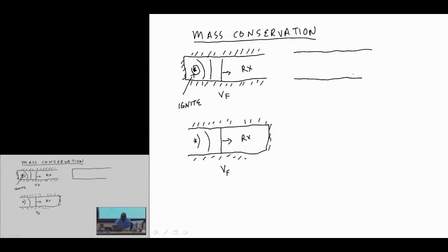So, we have this observed flame velocity. The assumption is that we have, in this case, again, just like in the bottom case, a burnt gas over here. We have an unburnt gas over here. So let's make sure I'm being honest here. VB is our burnt gas. These are our products. VU, unburnt gases. These are our reactants. And both of these are velocities, burnt velocity, unburnt velocity.